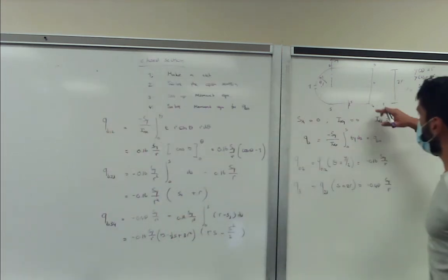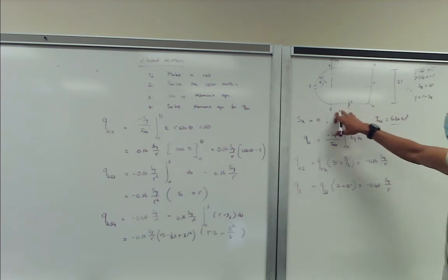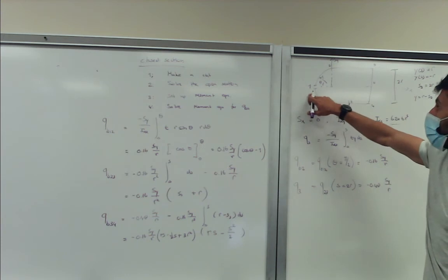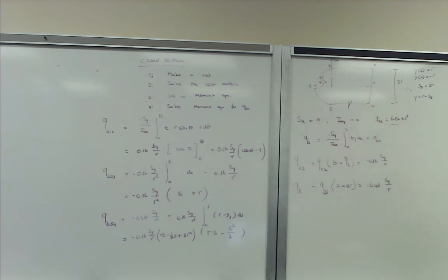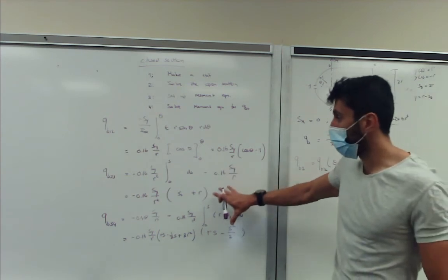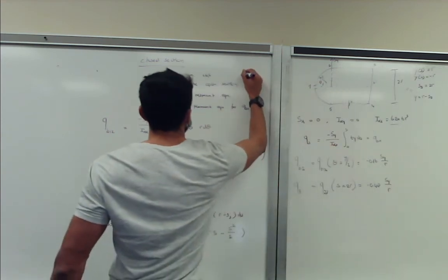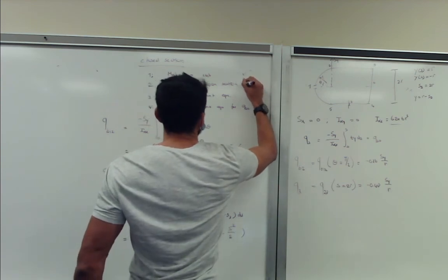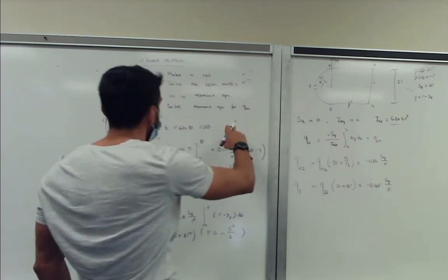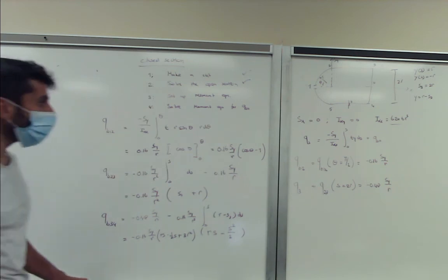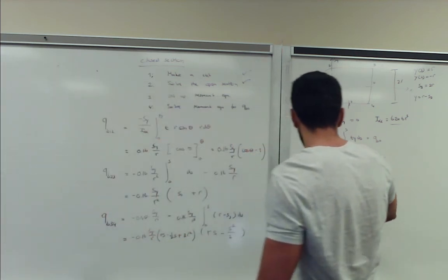And we don't have to calculate segment 5-4 because of symmetry with 2-3. We don't have to calculate 5-1 because it has symmetry with 1-2. So what we now have is all the open section shear flows. So we made a cut, and this is the check: we solved the open section shear flow. We now have to set up the equation and calculate the correction shear flow.